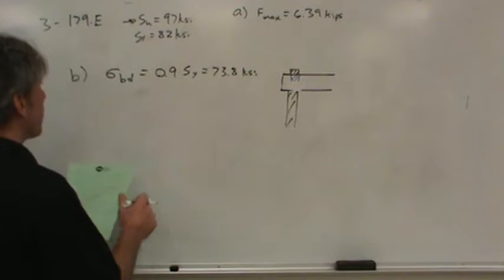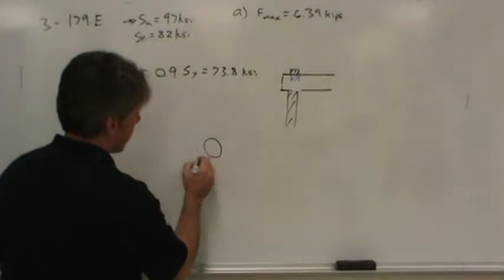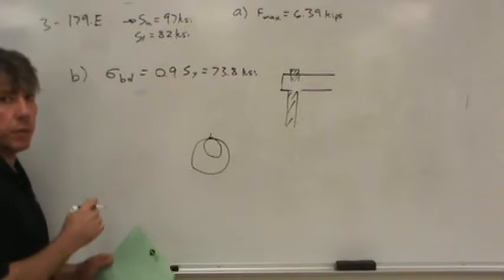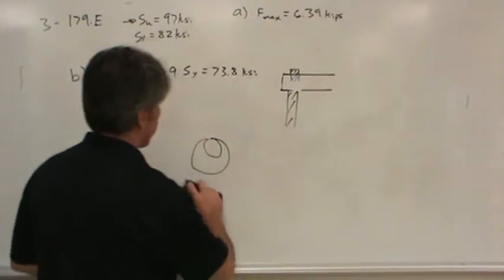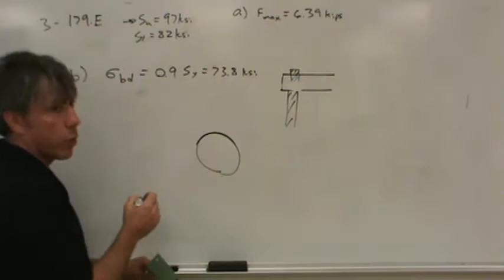Okay. Now, another note in that equation, page 151, if you turned away from it, go back, please. Actually, not that page, one page back. Page 149, equation 321. One thing that's recommended is when you have a pin in a hole like this, if the pin fits fairly loose in the hole, let me exaggerate the hole, then there's just one point of contact, and then we have Hertzian stress. Okay, but that's not what we're talking about here, because ideally we would have very close fitting, and so the pin and the hole will have contact at more than just a point.